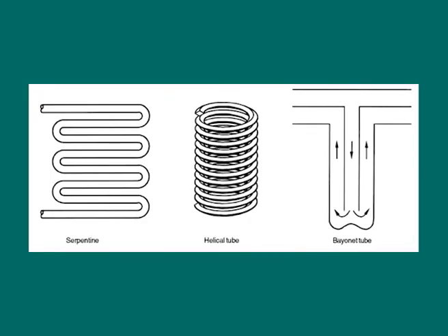Heat transfer rate associated with the spiral tube is higher than that for a straight tube. In addition, a considerable amount of surface can be accommodated in a given space by spiraling. Thermal expansion is not a problem, but cleaning is almost impossible.